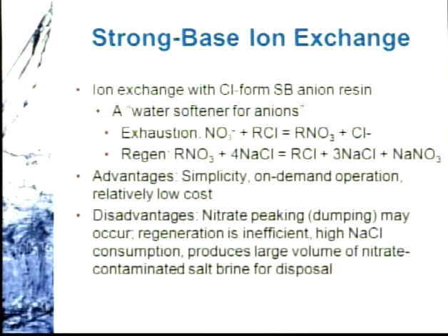That's not so much of a concern when you're doing primary nitrate treatment, but for other contaminants, for example arsenic or hexavalent chromium, if you apply a strong base anion exchange resin that operates past the nitrate breakthrough curve, you will peak nitrate off of that standard non-nitrate selective resin. Now, of course, you can use nitrate selective resins, and I'll get to that in just a second.